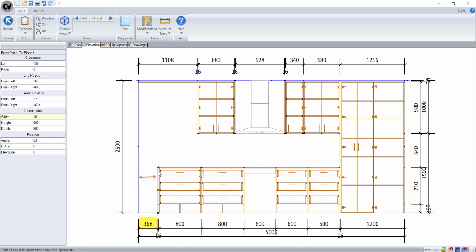Now by looking at the clearance from the base end panel below, and knowing that the distance of my benchtop overhang will eventually be 10mm, I can enter these amounts as an equation into the object width field to calculate my finished size. I'll then adjust my object height to be the material thickness that I intend on making the shelf from, and the object depth to be flush with the wall end panel, not the carcass depth.